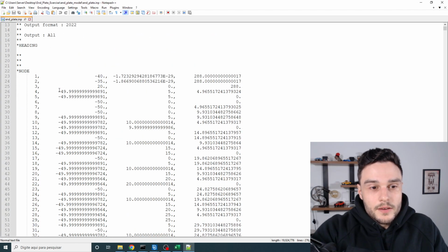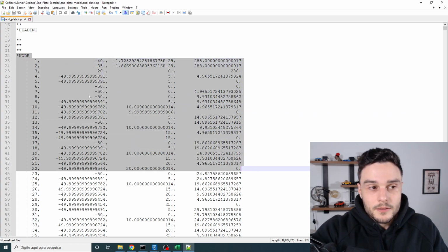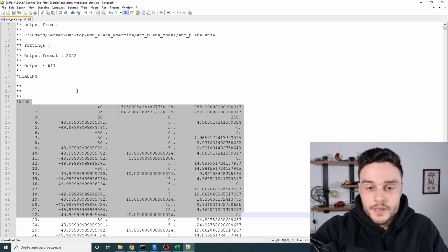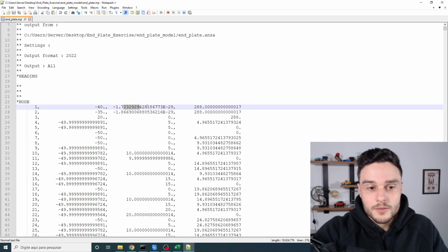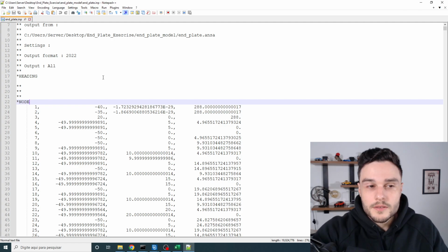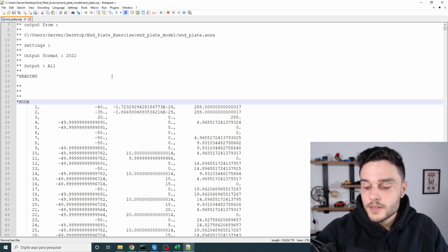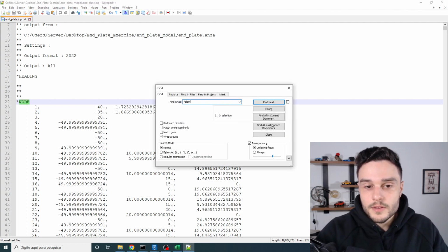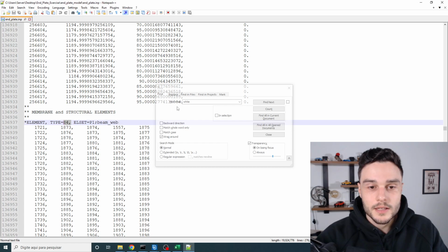And then in here we have all the definition of the mathematical model in a way that Abaqus understands. So we have the definition of the nodes. We have this command, node ID, X, Y, and Z coordinates. Anyways, this is something that I have shown to you many times before in the previous exercises, so I'm going to be fast. So we have the definition of element. You see, element type S4 for the quadrilateral elements.